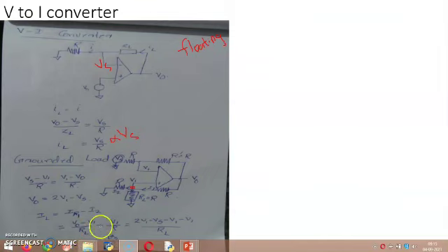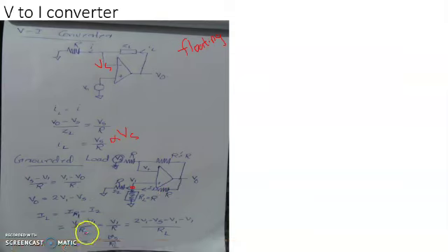By R actually. So IL equal to I1 minus I2. I1 is the current through this path, that is VO minus V1 divided by R, not RL but R. VO minus V1 by R minus current through this branch is V1 minus 0, that is V1 by R. That's equal to, R is common denominator, say R only.